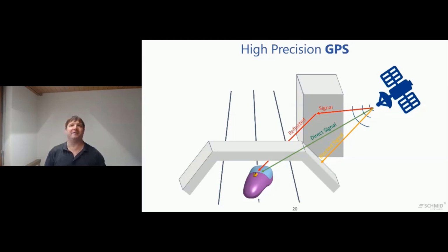At first it seems like an easy sensor acquisition, GPS data. However, you need to know that in order to get proper GPS signals, you have to have a direct view to 7 satellites, and this seldom happens on the track because sometimes we have high-story buildings beside the track, and we have bridges crossing over the track that lead to dropouts of the signal, or maybe deflect and reflect it, and this leads to faulty signals. And there were some funny incidents on the track. We saw the vehicle was really on the track, while on the big board of the visualizations it was moving in a nearby shopping mall.